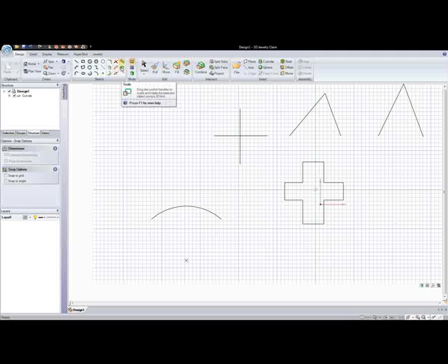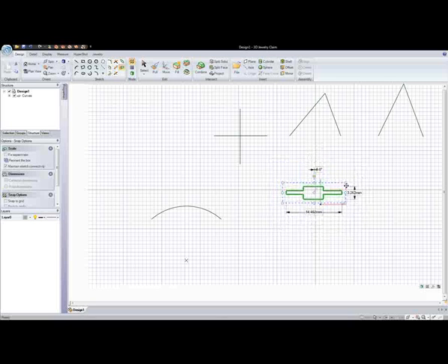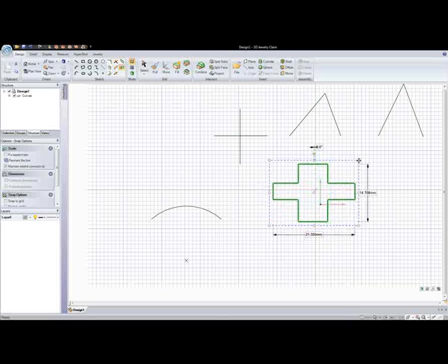Below that, we have scale. If I select on scale, I can either select the line or double click on the line to select the entire all 8 curves. Now, I can adjust my design and scale it and pull it in and out in different shapes. And it scales from that center point, as you can see.